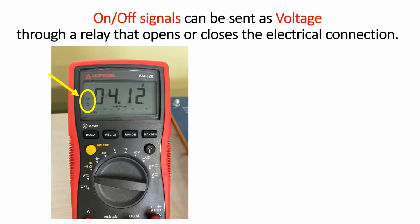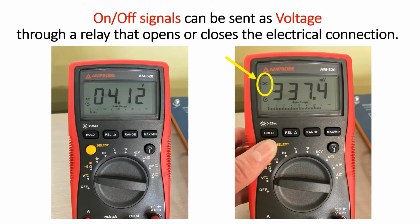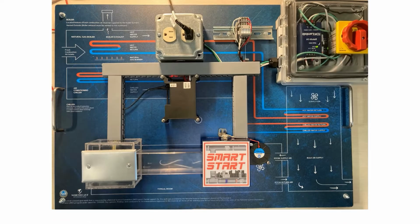Notice that AC is the default display. The fan and light on the trainer run on DC, so you will want to make sure that you push the yellow select button to switch the digital multimeter reading to DC. You will have the opportunity to measure voltage output signals as part of your BAS training activities in this class. The next several slides provide an overview of how to measure relay voltage control outputs from the controller to the fan.